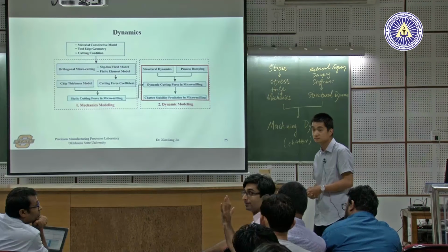Plus, what you have to do is make sure that there is total noise isolation. Everything that has a motor should be as far away as possible from the data acquisition. You can also detect the drift. First thing, before you start, let the dynamometer sit there for 3-4 hours, so at least the drift goes away.